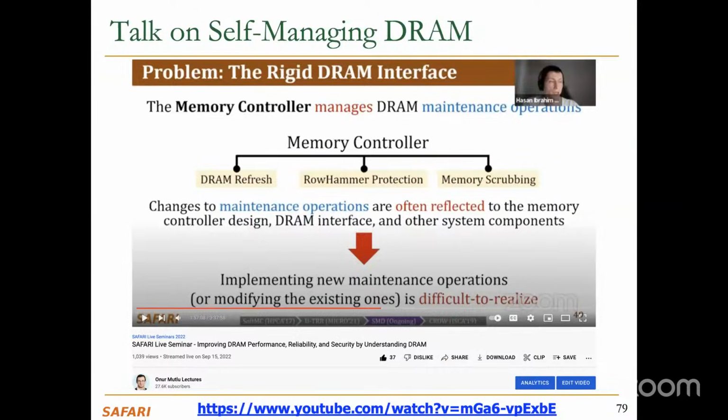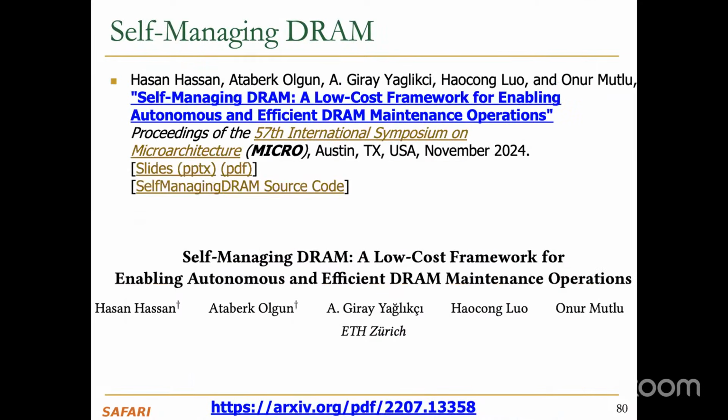Because alert has a very specific function. If the memory chip is really dying, it cannot work, for example, for some reason, you raise the alert. And if you start overloading the alert signal, oh, the memory chip needs time, so let's overload the signal, then actually the interface is broken. Well, it's already broken, but you're really trying to work with a broken interface as opposed to fixing the real problem. Okay, so this is self-managing DRAM.